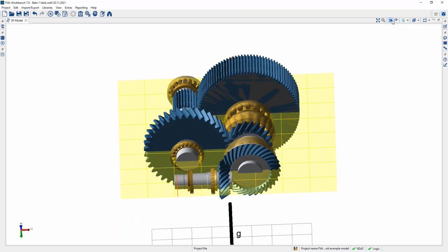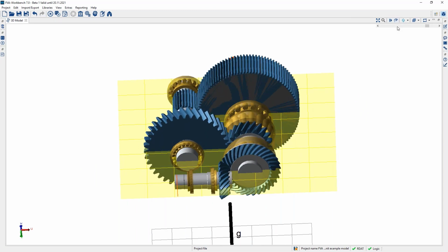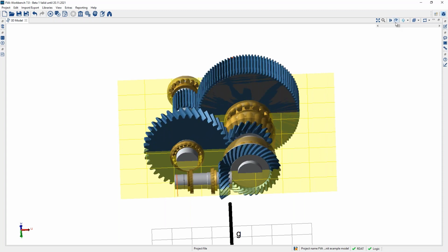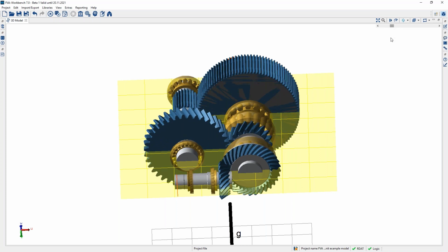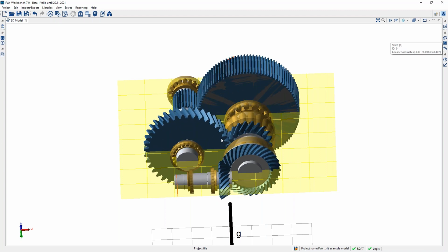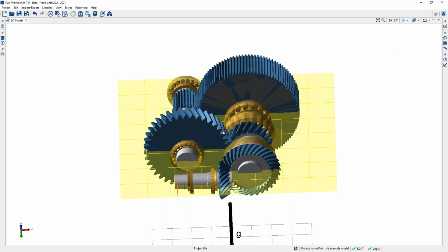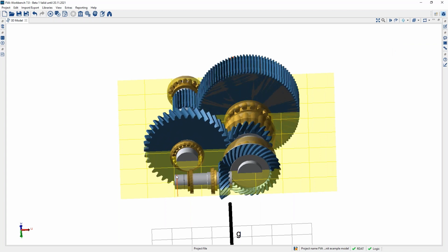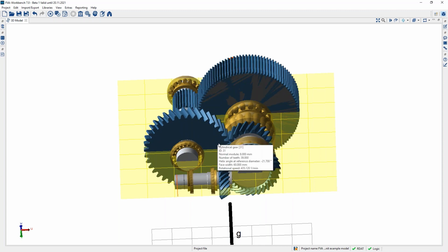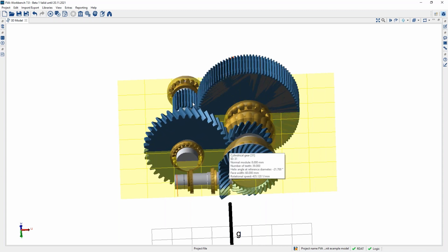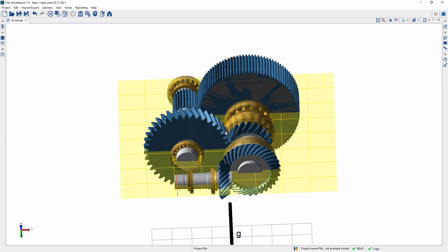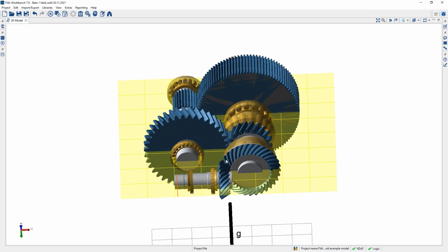Because if you run the simulation, maybe a little bit slower, you can see the rotation direction: the mesh is going out of the lubricant, and the lubricant will be fed into the gear mesh indirectly over the walls of the housing and over the splash inside of the meshing, here or here.